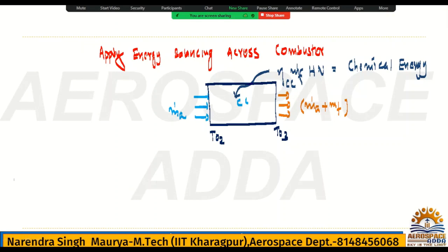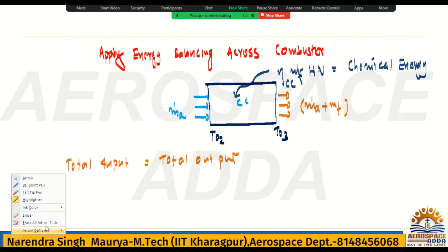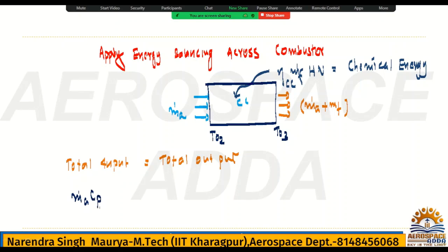Now, what is the energy balance? Total input is equal to total output. What is the total input? The total input is m dot a into, at constant pressure, cp of air, because it is air, into the temperature t naught 2.